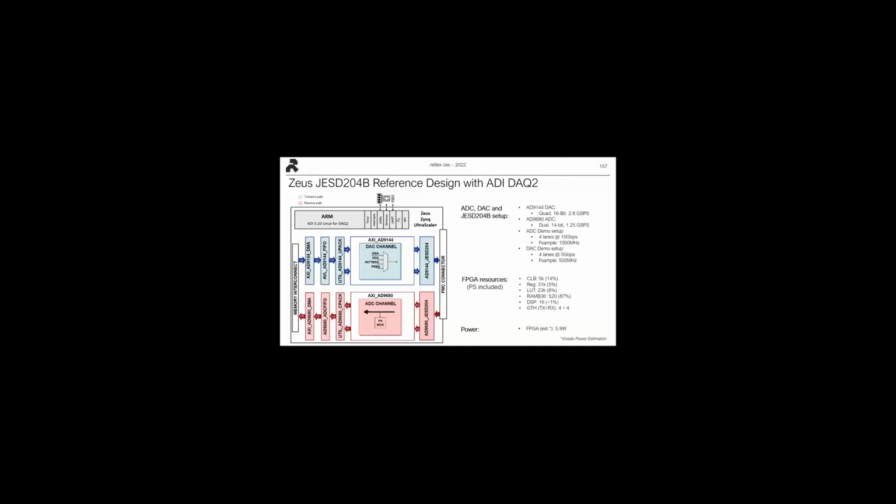So why the difference here? In the design example, in the JESD framework on Analog Devices, for the Zynq circuits, we are using 2 different PLLs. One is the QPLL, the other is the CPLL. But with the different line rates, we are running at 2 different frequency ranges to generate the PLL. So we can't generate the same frequency outputs for that module.